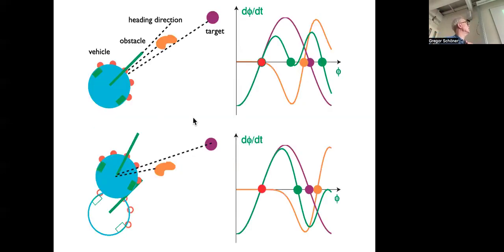Here's an illustration of that. For instance, here I'm using this trick of inverting the axis because it is too complex to track otherwise. So let's say initially I'm in this configuration, and I took that actually from some actual simulation, but it's from a different approach, the subsymbolic approach. So here's the target, here is the obstacle. And so I had inverted the axis, so the target is to the right of the obstacle. So the target contribution is this lila line here, and the obstacle contribution is that ochre or brown line here. And the green is the sum of those two.